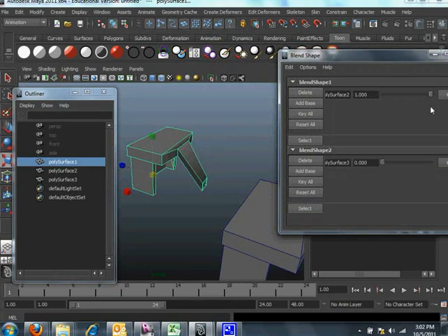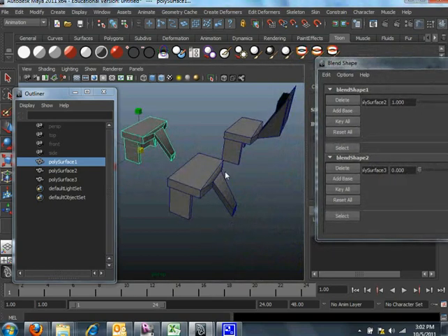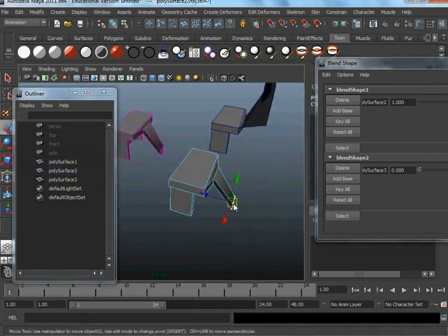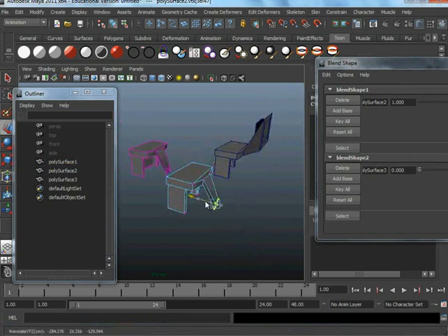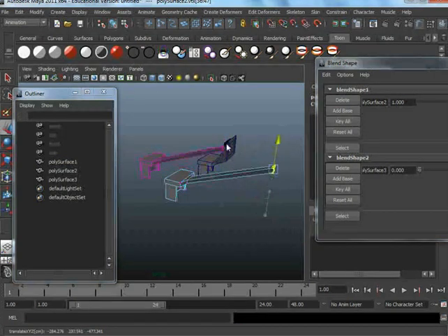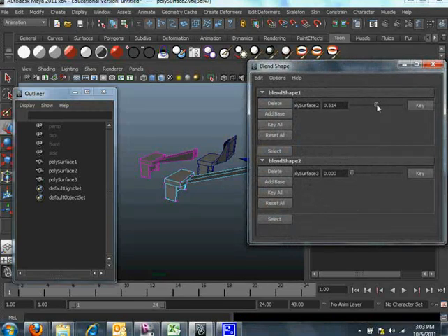You have this kind of parametric control on these components. Okay. Another really cool thing about this process is because everything is based on the history. If I think, well, parent A, I think the shape doesn't make sense. I want to change the shape to something else. As soon as you update parent A, you'll see that children will go with it. If the weight is 50%, you got halfway.